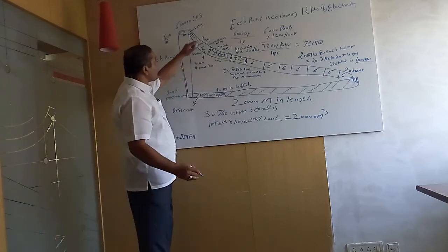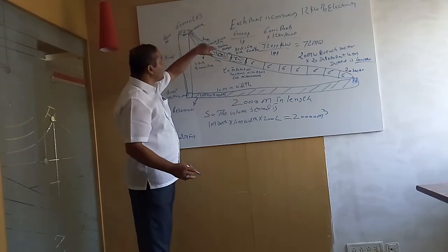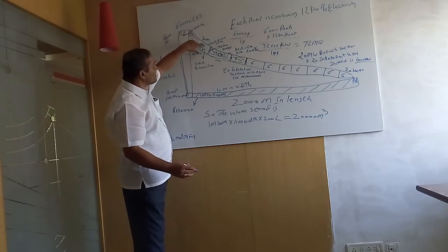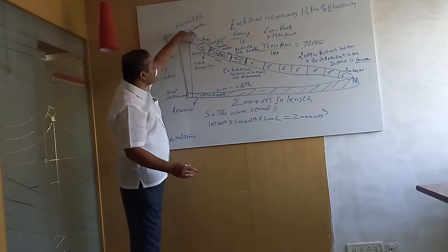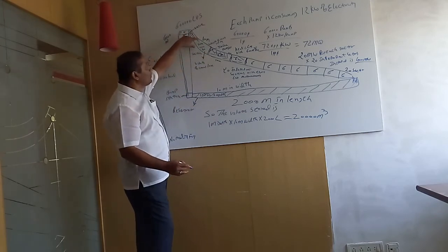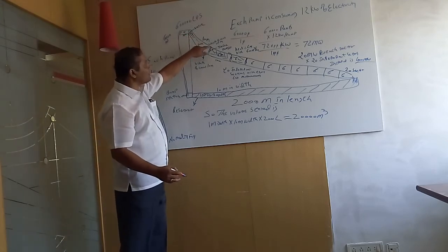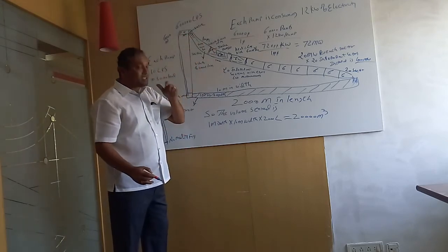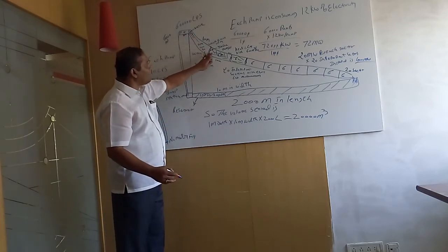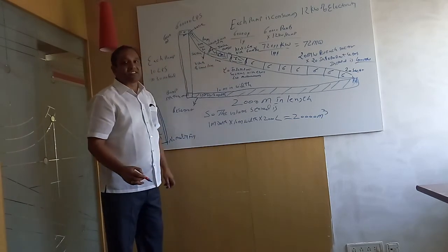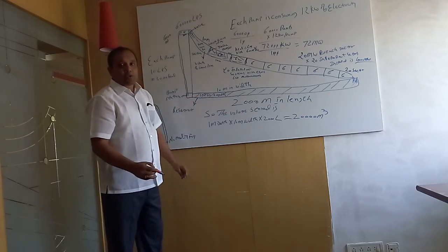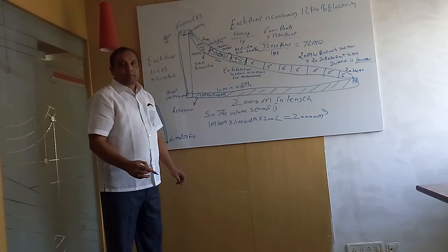So in this particular thing, what we have designed is, the head is continuously available at each sector because the depth is 6 meters and the discharge is 600 meter cube, because each sector will be storing 6,000 cubic meters. 10 seconds, 6,000 cubic meters is stored, and 600 meter cube discharge is done every second. Thereby for 10 seconds automatically every sector is operating and energy is generated. So in this way the cascading system is more applicable to areas where we really require more energy.